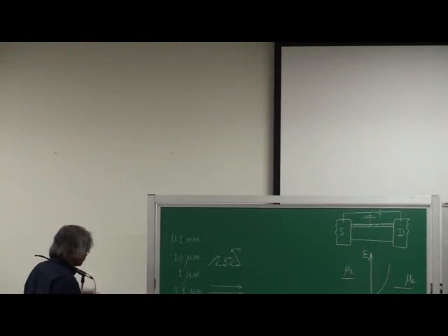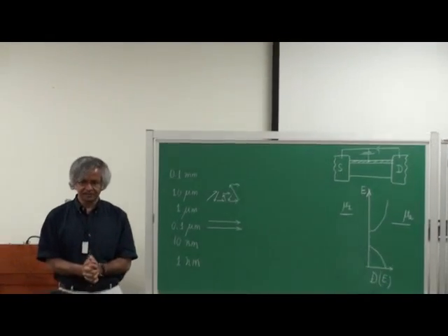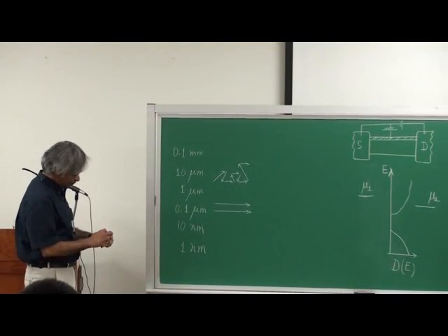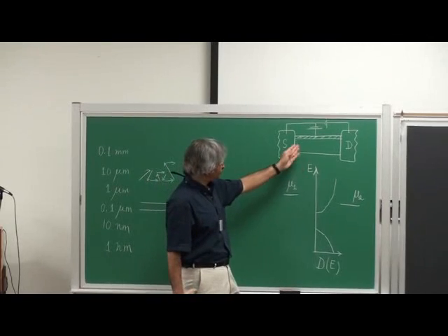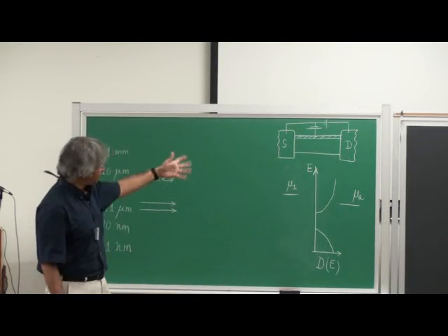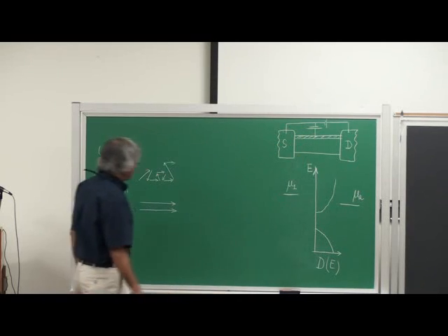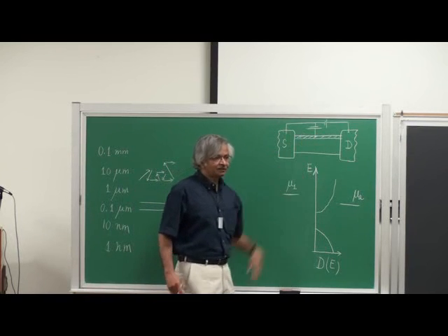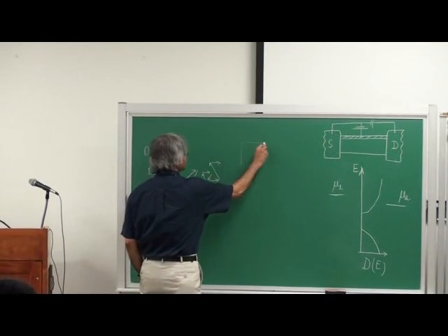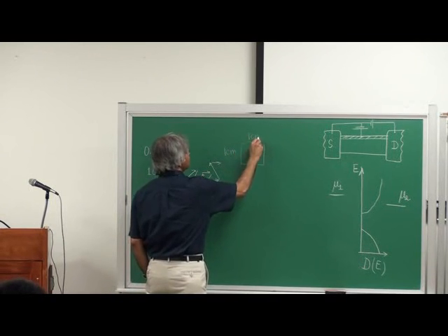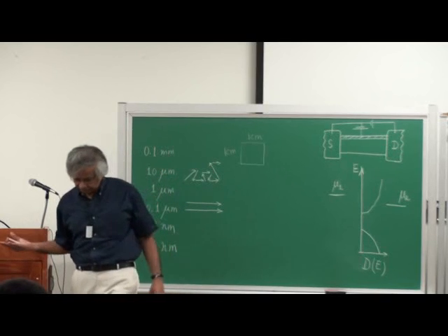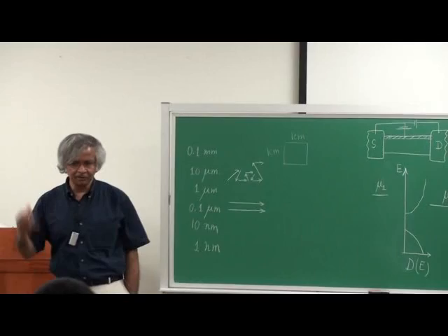years now. There's been this continuing trend because you can pack so many of these transistors into a computer. And the way you would roughly see the numbers is that the basic device here is this transistor, which consists of a channel with two contacts across it, and this third terminal allows you to change the resistance. So it's basically a resistor which can be controlled through a third terminal. And the question is, how much space does it take to put a transistor? Well, roughly, if it took about 10 micrometers to put one transistor, then if you had a chip that was 1 centimeter by 1 centimeter, you would be able to fit about 1,000 this way and 1,000 that way. And that would mean you would have about 1 million of them, which is about where things were, say, 20 years ago.